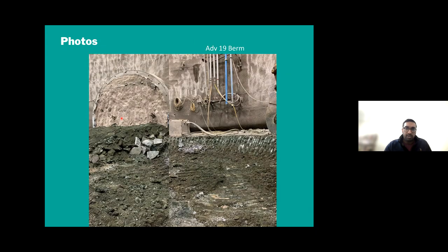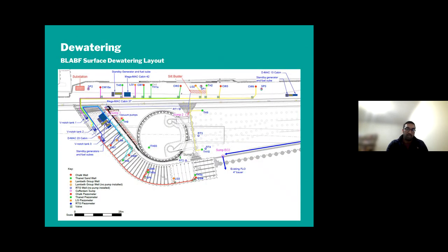One of the main considerations for this shaft, and I think that's another key thing, is that we associate SEM with just tunnels only, and obviously there are a lot of examples of tunnels, but shafts are another big structure that is used a lot in London. Possibly it helps that London clay has a good stand-up time, but this shaft in particular was driven into a very dense water-bearing granular strata right at the base, and so dewatering for this was very important.